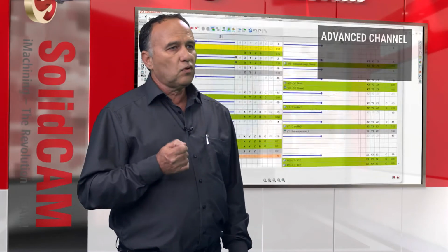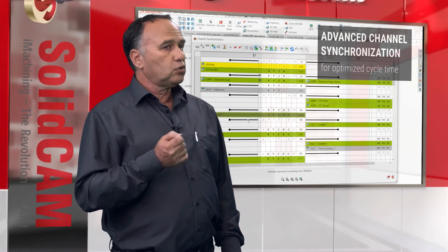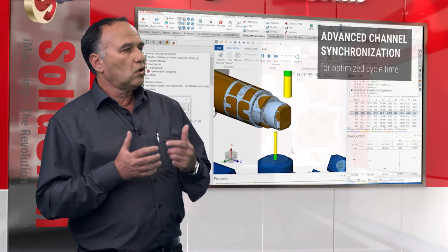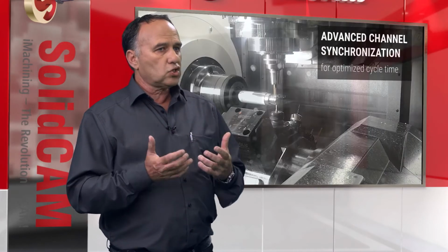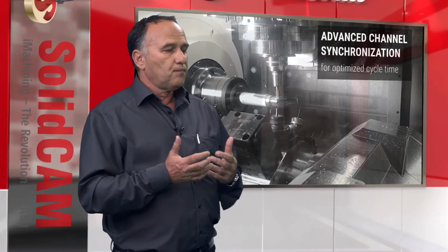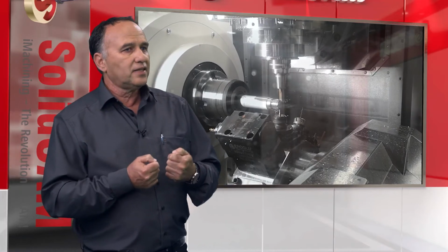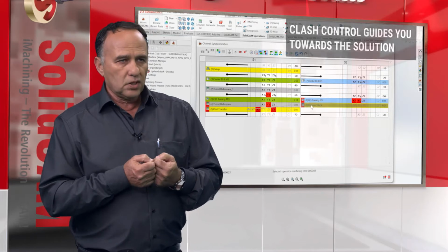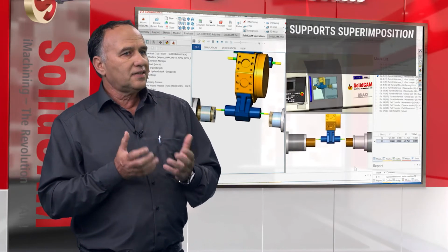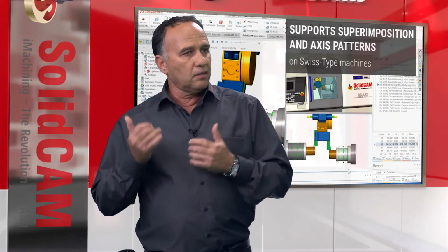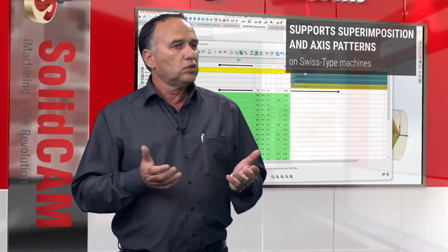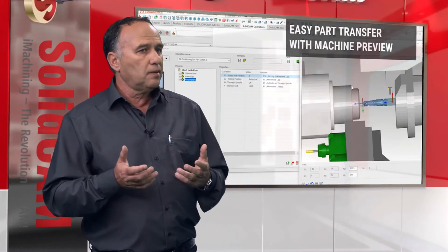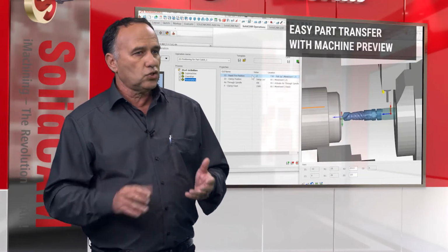And the second level in the CNC machine shop is the level of the CNC setup operators, who are responsible for getting the G-code file, the list of tools, a chart that's showing a part clamping, including the location of the arms and the positions they need for the setup. And they need to perform at the end an initial dry run, step by step at the machine, to verify that indeed the CNC program, which was prepared by the programmer, is error-free, with no collision, and that the CAM part will be executed without problem and, of course, in the right dimension.